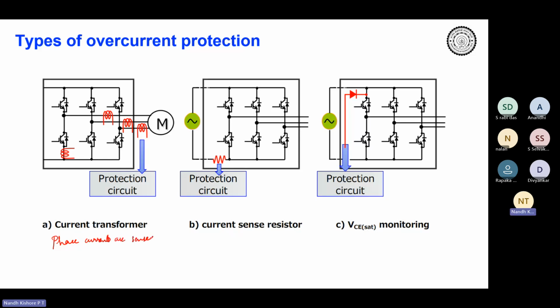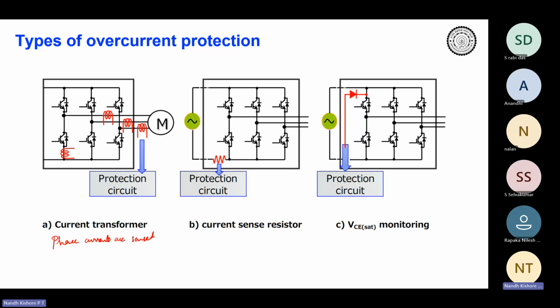And if you see that the phase currents are increasing beyond some particular level, you understand that there is some fault, correct? And you obviously know that since the phase currents are essentially the device currents, the device currents are going to be somewhat the same. Or you can also have the current transformer directly in the switching leg itself. So essentially you will be measuring the device current. Okay. So this is one way of doing it.